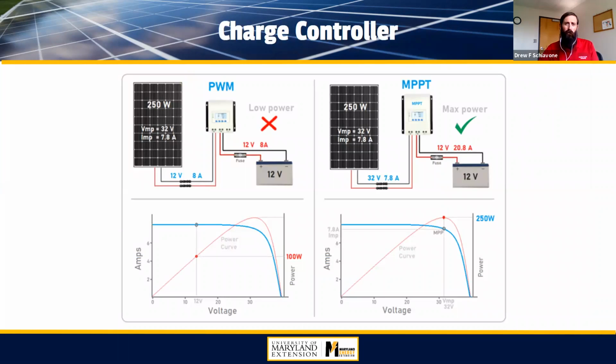The charge controller is important as well. I mentioned this previously, but a charge controller really protects your battery from being under or overcharged, so it's not going to fail. There's 2 main technologies out there: pulse wave modulation and the MPPT, which is more popular now and has its benefits. For one, you're able to send more power directly to your system, and it gives you a little bit better control over the size of the panel matching the battery. But again, we'll talk about this at a later date.